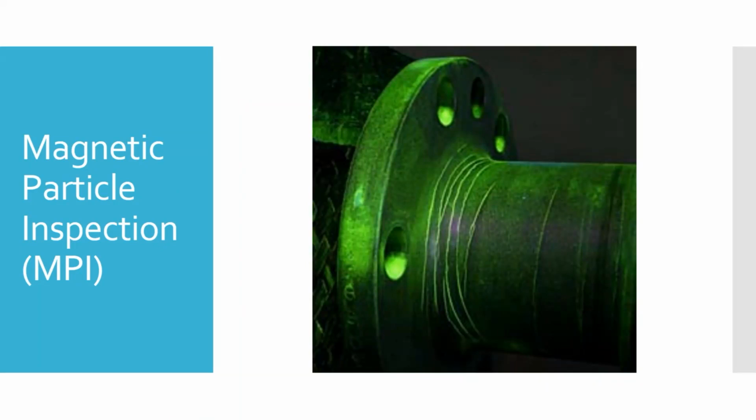With classifying: relevant, non-relevant, false. What kind of indication would those cracks be? Those are a relevant indication. Do you see anything else going on here? Any other indications where the dye is glowing? What about the bolt holes? They're glowing. Why are they glowing?